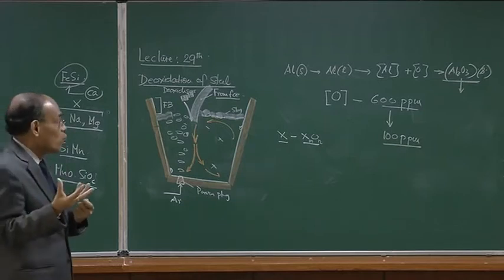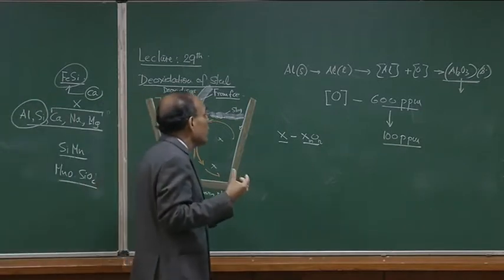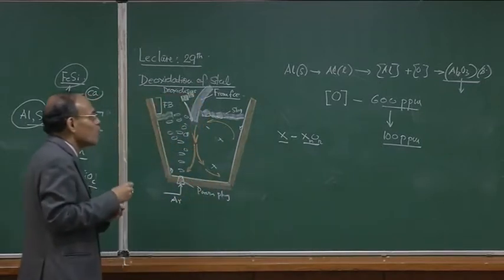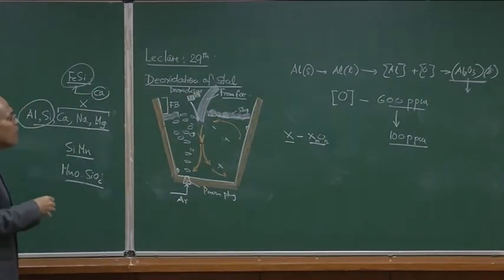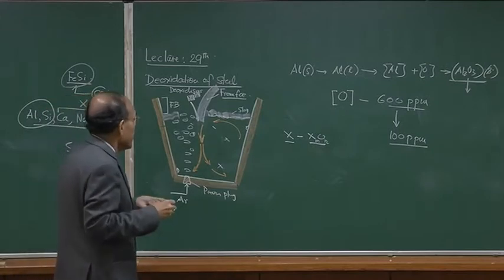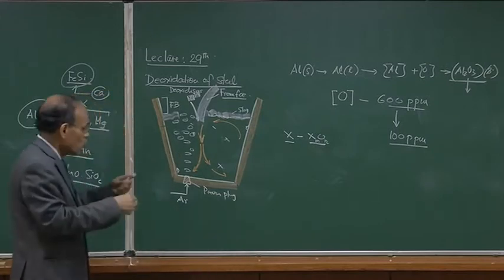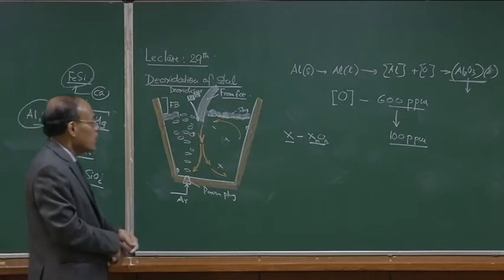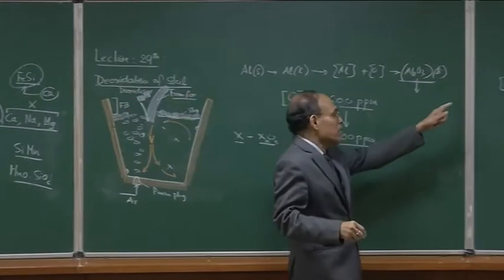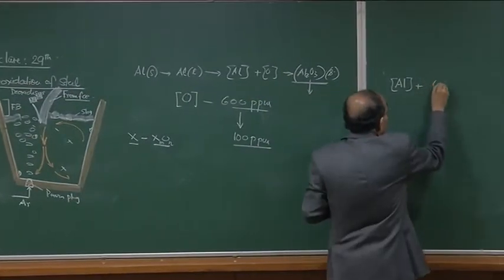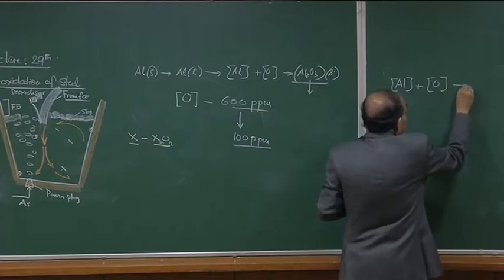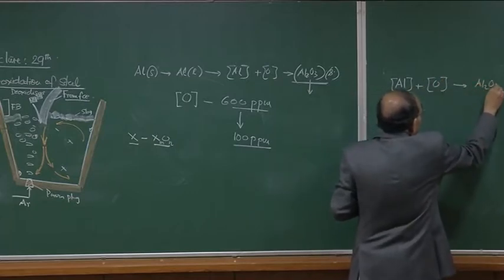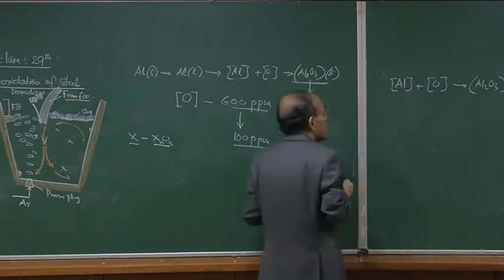Silicon of course does not melt in steel, aluminum melts in steel, and it has a melting point of close to, I think, 800 degrees centigrade. So the melting is very rapid, and dissolution too is not slow. So the aluminum is available in the dissolved state, and so is silicon, and then the reaction takes place, Al2O3, the solid products form, and nucleation and growth is as I have indicated.